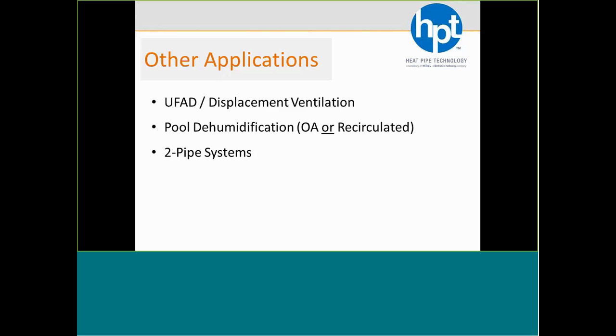So the wraparound heat pipe is not only going to reduce that load like we've been talking about, but if you size it to handle that reheat for you at the small loads and add the valves to it to shave that extra unwanted reheat at the high loads, now you're getting that reheat for free while taking all that chilled water from the two-pipe system.